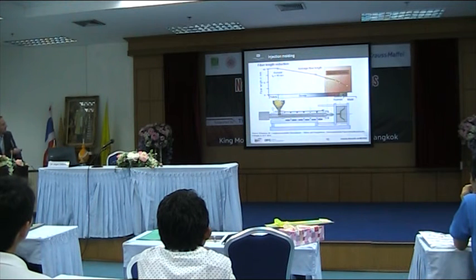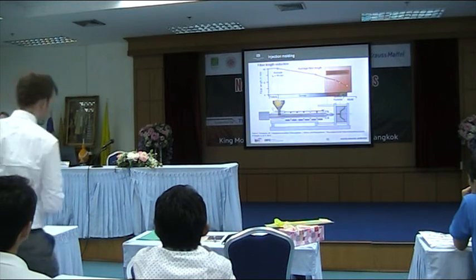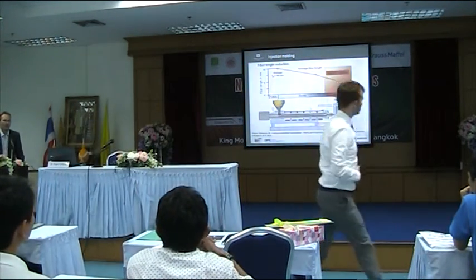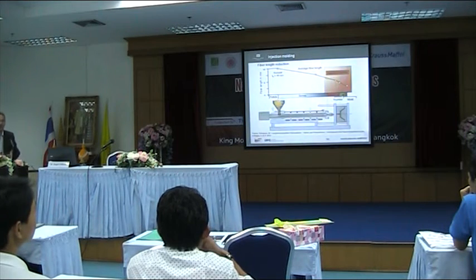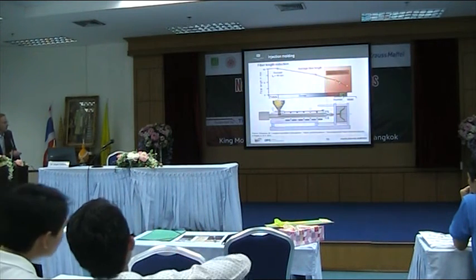You start with a typical long fiber pellet with a fiber length of 10 millimeters, and then you go into the plastification process. You have a high shear stress in the twin screw extruder due to the mixing process and the metering process, the melting process of the granulate.